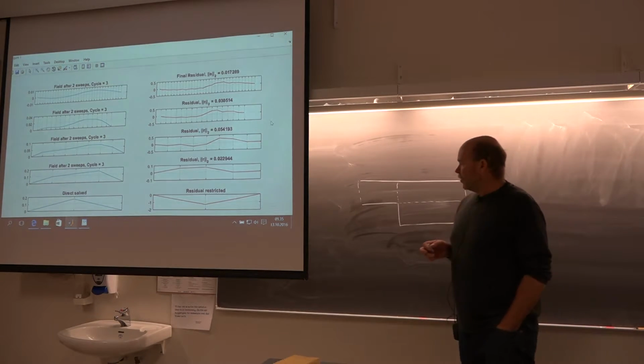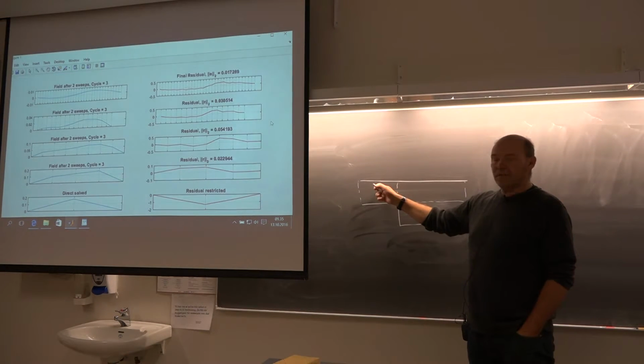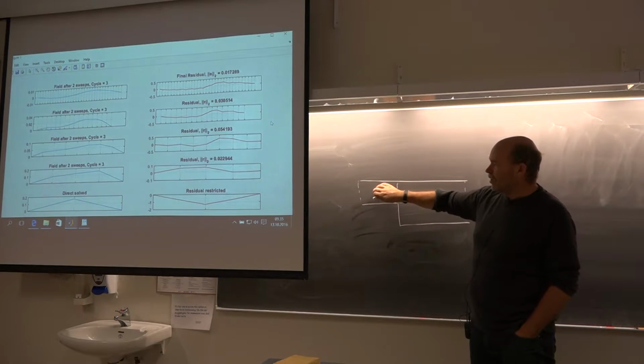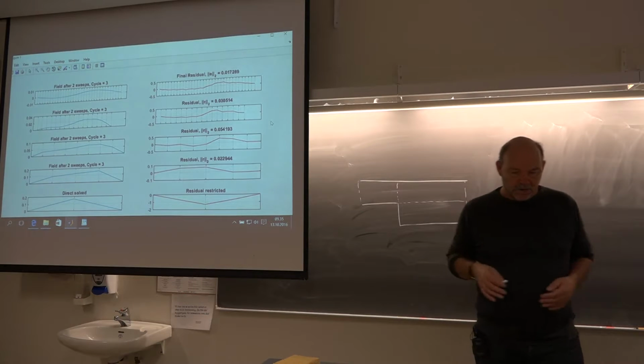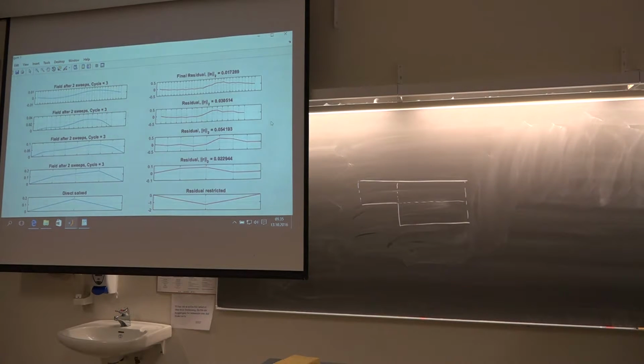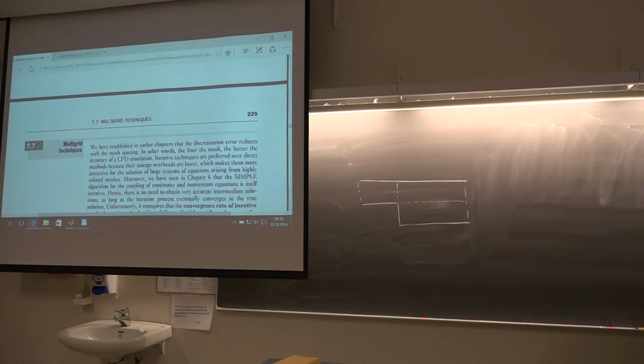You can also operate with so-called multi-block multigrids. Within one block, you have multigrid alone, just inside one single block. Then the different blocks have to talk to each other. It's a little bit advanced, but yes, it exists. So multigrid, yes, that is an option, and I would say quite popular as well, but tricky to use.